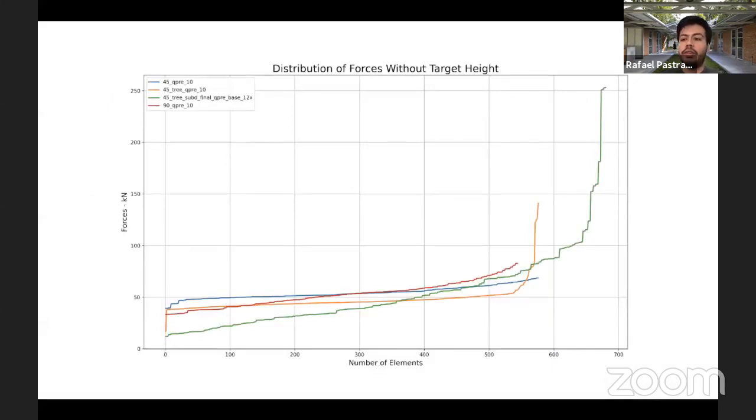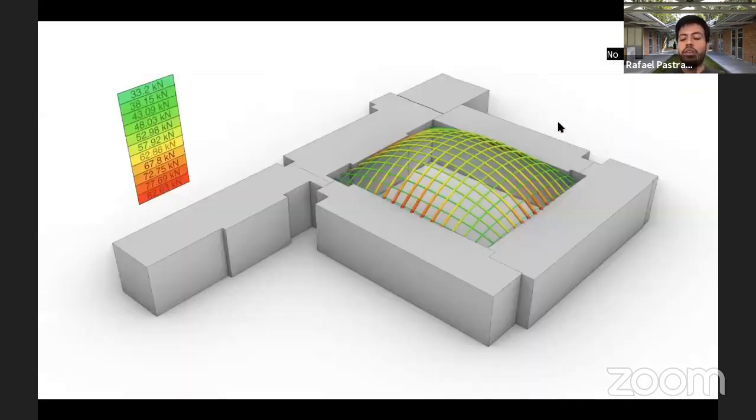Interestingly, we plotted the total load path of the four alternatives, and in this graph you see that option 4, which is the selected one in green, looks a little bit disadvantageous here. But the situation is that for the first study, we didn't limit the total height of the form found solutions.